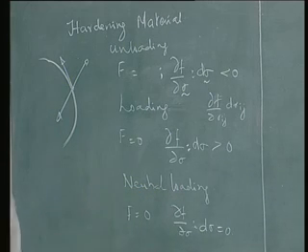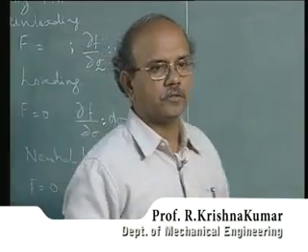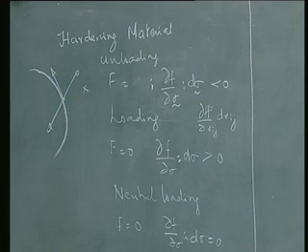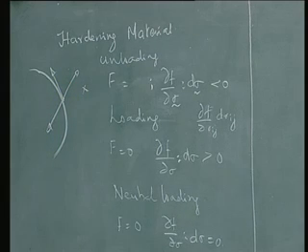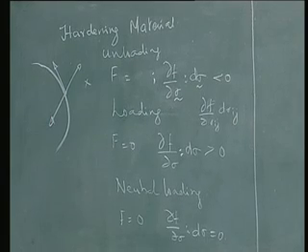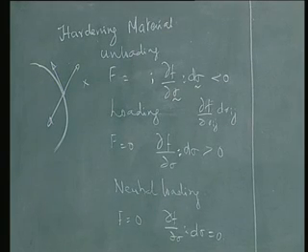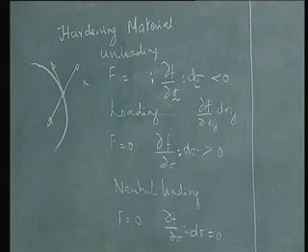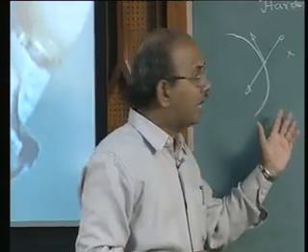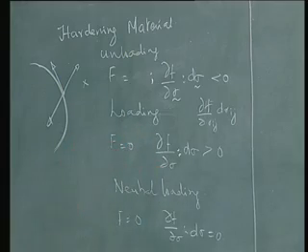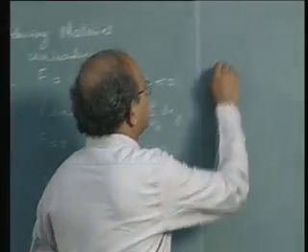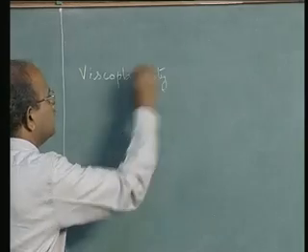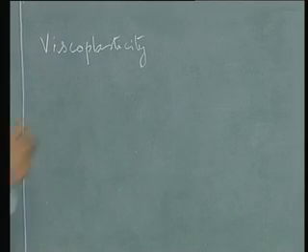Towards the end of the class, there was a very good question as to whether a point can lie outside. In fact, I made a statement subtly that we are looking at rate independent materials. So does it mean there is a rate dependent material? Yes, when materials are subjected to very high temperatures, they will have another effect added on to this, which is called the viscoplastic effect, or viscoplasticity, the governing phenomenon for bodies subjected to creep.